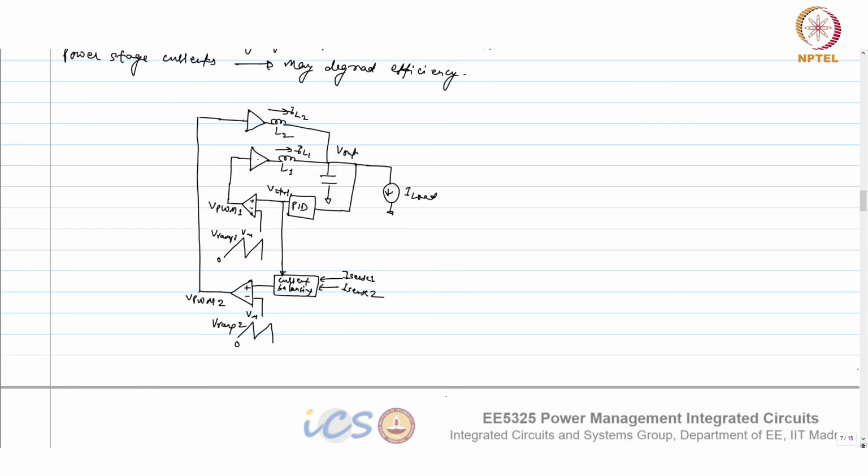Yeah, it will do. So in this case, it doesn't care about why it is. But when it balances with a different RDCR, the impact on efficiency is very small compared to if this mismatch is due to the duty cycle. And you can do that calculation, because that RDCR is already very small. So that mismatch will hardly impact, 1 or 2% mismatch or even 10% mismatch. You will see the efficiency impact won't be that much. But if you create a 1% difference in the duty cycle, that efficiency impact will be huge actually.